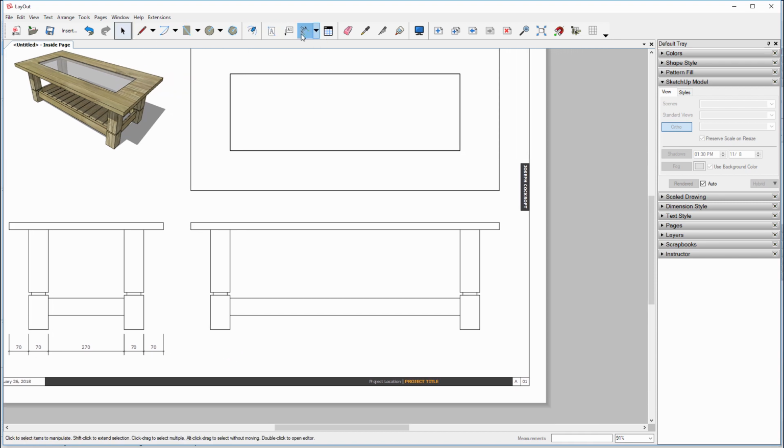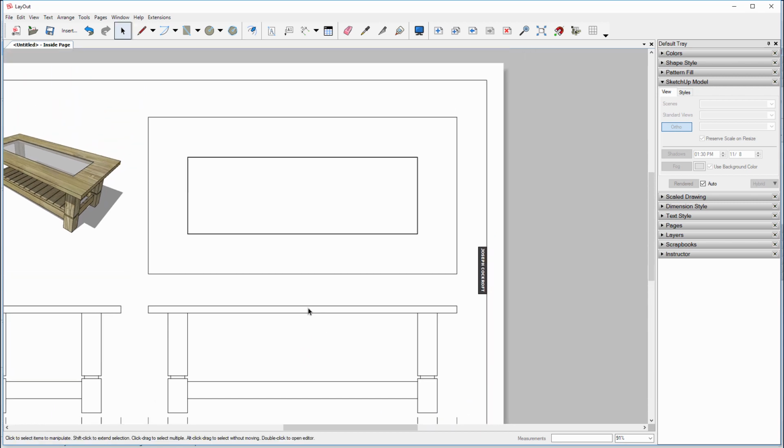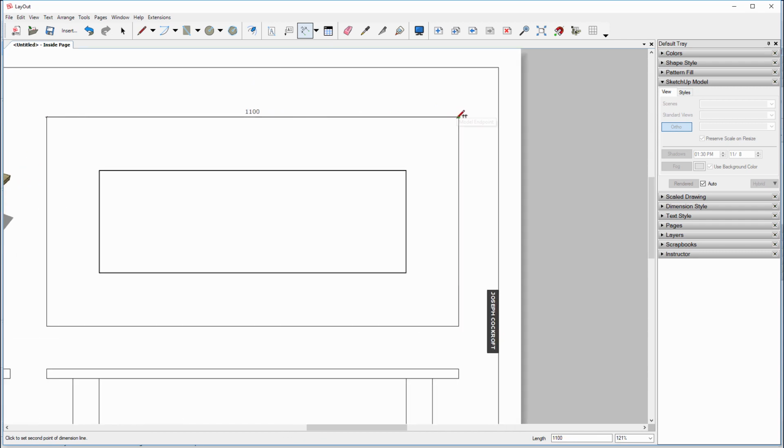So I'm just going to go through and add those dimensions quite quickly. Double click, double click, double click, and double click. Spacebar, double click on the dimension, drag it down, spacebar, double click on the dimension and drag it down. Lastly, just the tabletop size, we're going to go to dimension again and zoom in sometimes. If you're not able to pick on the endpoints, make sure that you have object snap on. You can also get to object snap by right clicking in grey space.